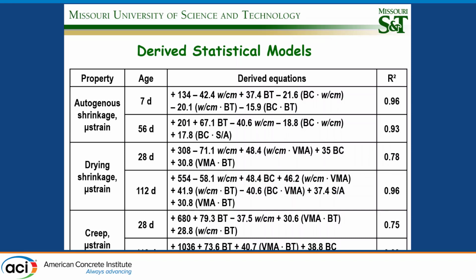And they are listed in order of importance. So the first one is water binder ratio. You see it's very important. That means it's the factor that is the most important. And granted, if you change materials, the response will change. But what's interesting is knowing what the trend is. So if I were to take this and say, okay, I'm going to use the slag cement or I'm going to use different aggregate, I know what are the two most important parameters to go and do some testing and mixture development.